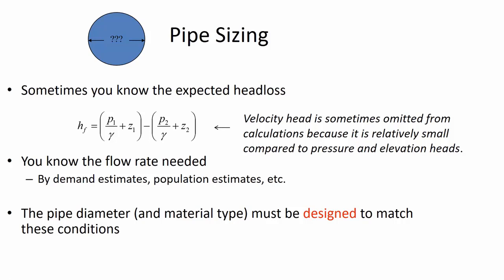On our first class day, I gave you a sneak peek of the project that we're going to do this semester, and that's a network sizing. The pipe network sizing is always juggling how much pressure you've got at a certain location versus the pipe size. If you make the pipe size smaller, then you're going to be reducing how much pressure there is at a location. And so here, this idea of finding the required diameter is going to be matching ever smaller pipe diameters until you have the head loss that matches those flow conditions.